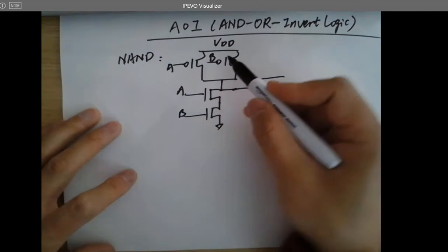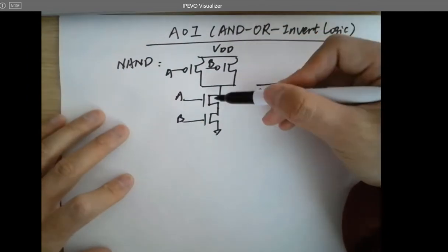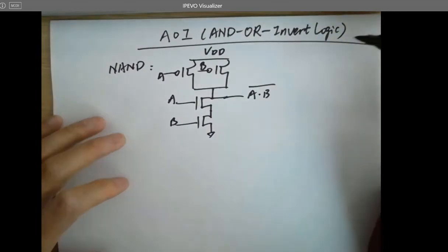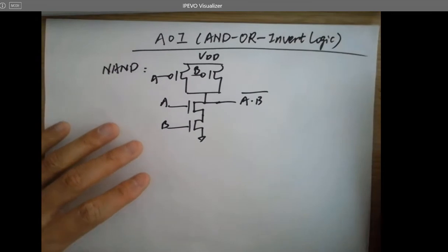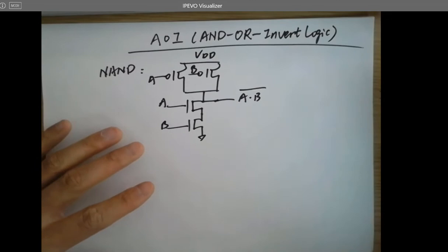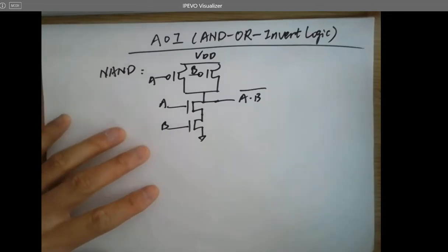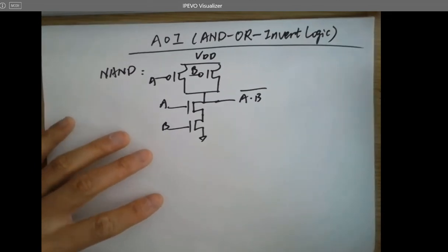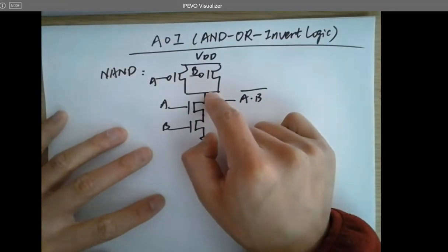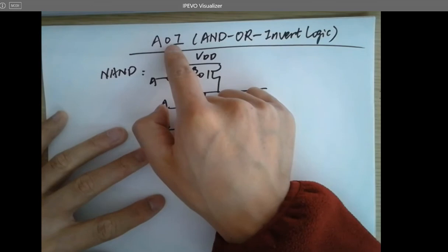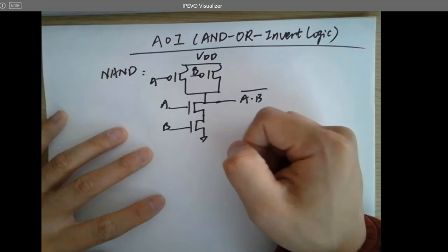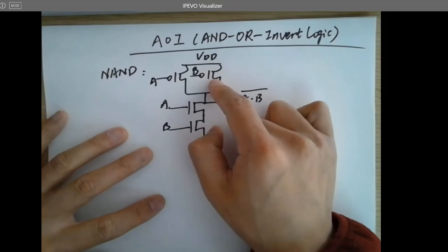So for NOR, you just put the 2 PMOSes in series on the top and 2 NMOSes in parallel at the bottom. Here's one thing you want to memorize because it's been verified so many times. Every time you use it, it's going to be correct. So the best way to implement it in the future is just to memorize it. After you understand this, keep in mind, every time you are applying AOI logic for a complex logic expression, use CMOSes instead of using gates.